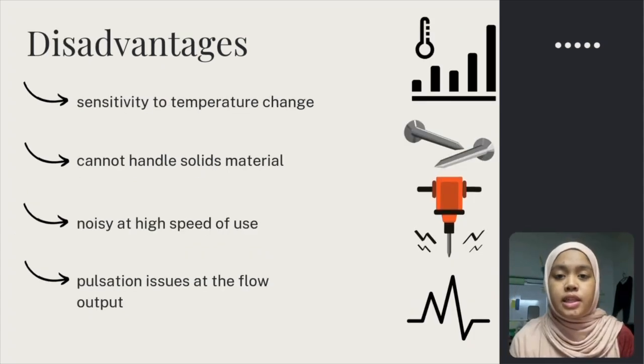There are also some disadvantages of this gear pump. First, it is very temperature sensitive. It may cause thermal expansion of the gear and may affect the performance of the pump. Second, this gear pump cannot handle solid material. It can damage the gear pump's internal parts because it is not designed to handle rough material.